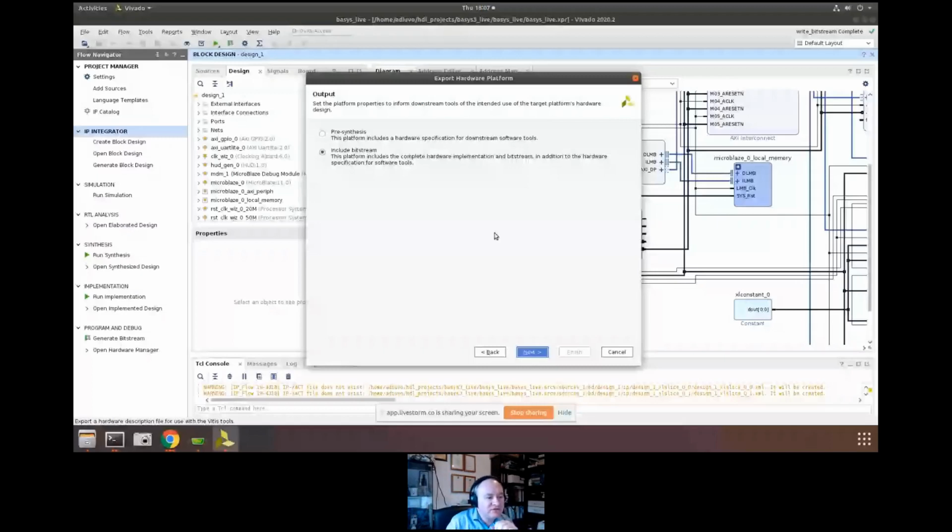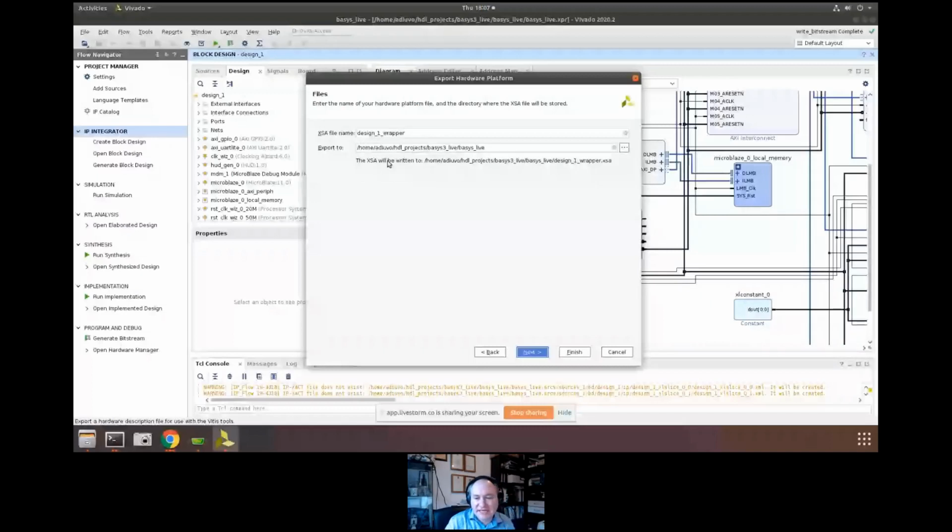So we're going to include the bit stream in this, and then we're going to leave the names and the location exactly as we want it to be seen there. So we're not going to give it any fancy names, and we'll let it export to where Vivado was going to export. And what we'll do is we'll click on Next.